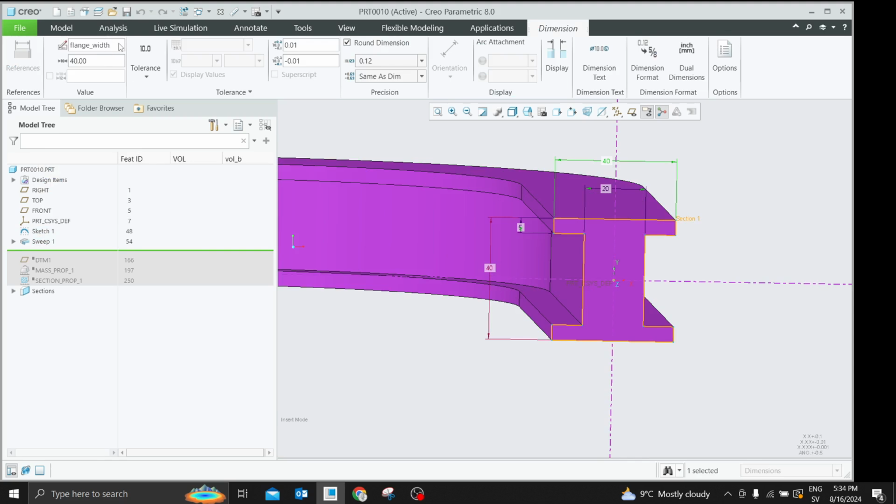This one might be SD something, sketch dimension, as well as height. Just name the parameters you want to change. Most of the time height remains constant, but you want to optimize web thickness, flange length and thickness. Then let's go back.